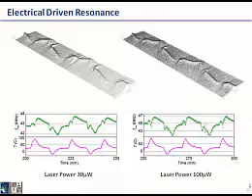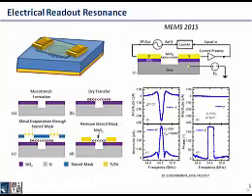And here are the raw data of the resonance frequency. It didn't show up very well, but basically in this direction, I'm sweeping frequency. This is my time axis, and you can see the resonance frequency switching between different states. And I'm checking with different laser power and confirm that my laser power isn't affecting the switching behavior I'm seeing in this device. So naturally, it would be nice if the readout can also be done electrically. So here, for this device structure, we can actually realize both electrical actuation and electrical readout.